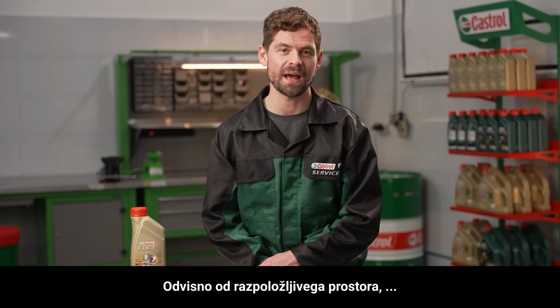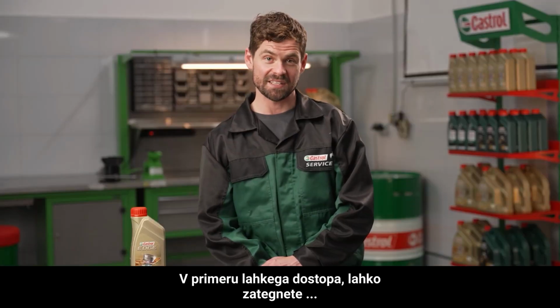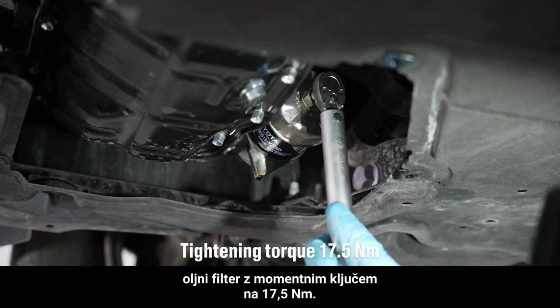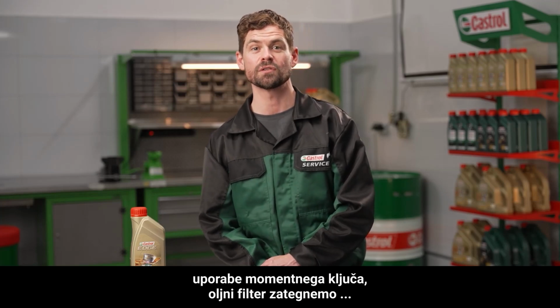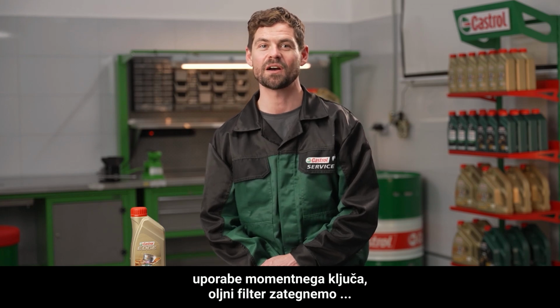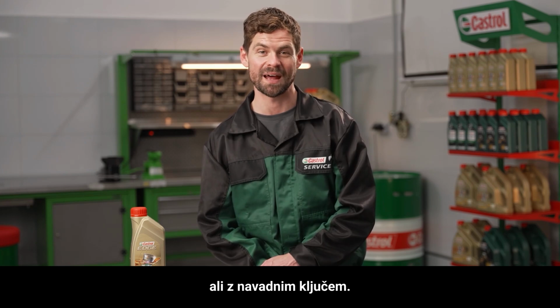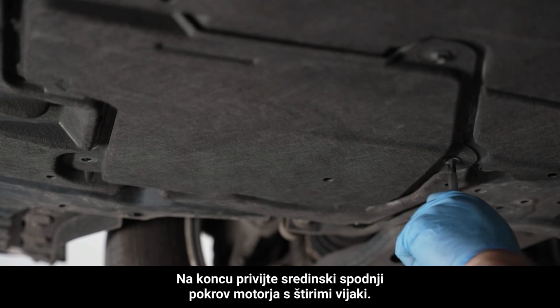Depending on the available space, we can choose one of the following methods. In the case of easy access, you can tighten the oil filter with a torque wrench to 17.5 Newton meters. If the amount of space available does not allow the use of a torque wrench, we tighten the oil filter with a 3/4 turn by hand or with an ordinary spanner. Finally, tighten the center under engine cover with 4 screws.